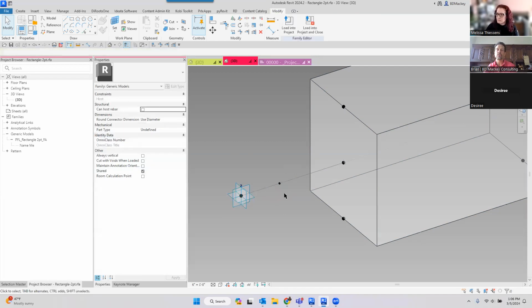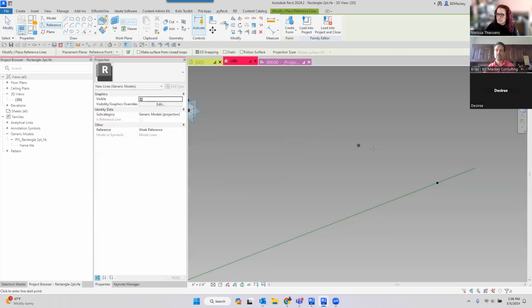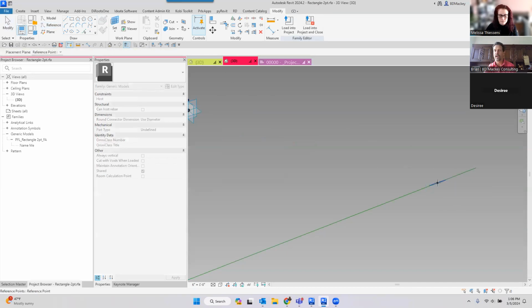Because the other thing you can start to do is host points on other points. So if I wanted to draw a reference point on this one, depending on if I wanted it to go up, down, right, left, forward, or backwards, I can set the work plane of each point because each point has 4 different work planes. You can see my reference line is twisted here, but you get the point. So I go vertical to this, I could go horizontal that way, horizontal this way, whatever I want to do.